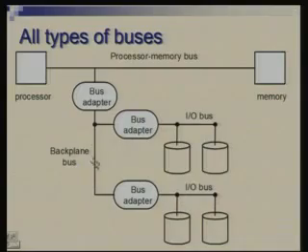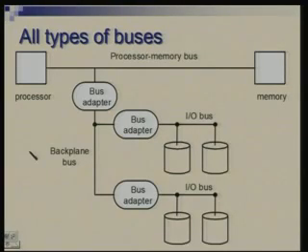Yeah, it's managed in terms of time sequence. So as I was saying, coming back to the same figures, suppose the backplane bus is able to carry data at the rate of 20 megabytes per second. Just for the sake of argument, let's say each of these is 1 byte wide, which means that every 50 nanoseconds each byte of data occupies the bus.